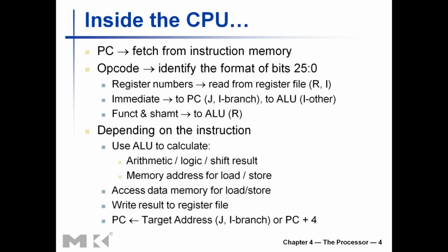operands. Then if it is a load or store instruction, once you have the address calculated, you need to access the memory, access the data memory. Note the difference, data memory here, and perform the load or store operation, read or write to or from the memory.